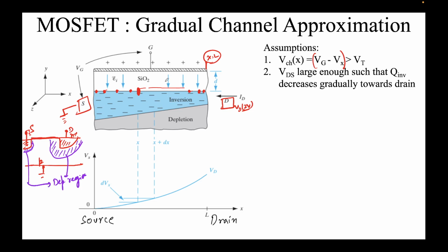Now, the depletion region that is here is not just due to the effect of the gate, because the gate is applying a vertical electric field in the negative y direction, but the depletion region will be cumulative of the electric field due to the drain as well as due to the gate. Hence, this depletion region is enhanced on the drain side, which you're seeing in this cross section. The depletion region of the source is smaller, so more of the gate's effect can now go for the inversion, because this is depleted enough. Now it can simply start the inversion.